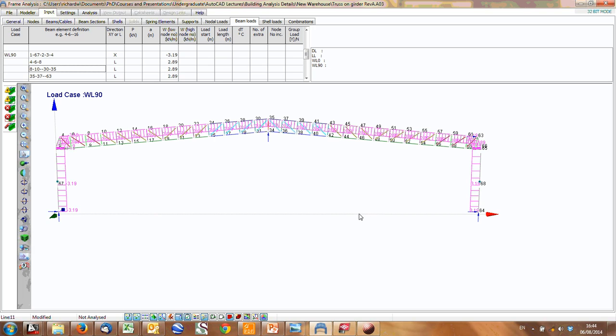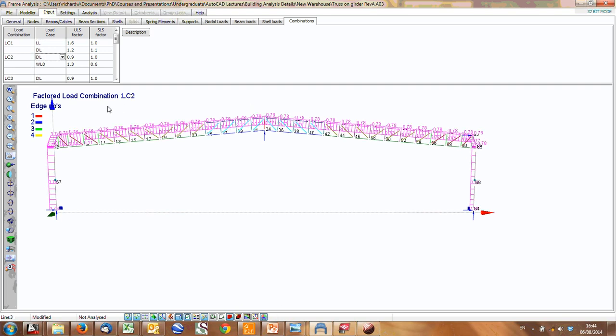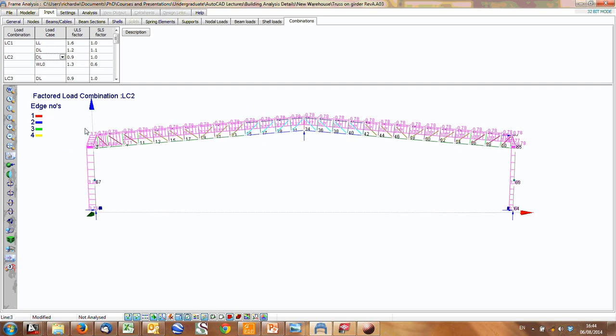You have various load conditions. Sometimes it gets a bit much, all the load conditions. So often the older engineers especially, they just do one or two load combinations, but the new loading code does provide for a variety of loading conditions. But let's have a look at this wind loading case. If we've got horizontal, up, but let's combine it now into various things. We have our load cases here with dead load, live load, etc. And this will also consider some notional horizontal forces if required, or second order analyses.